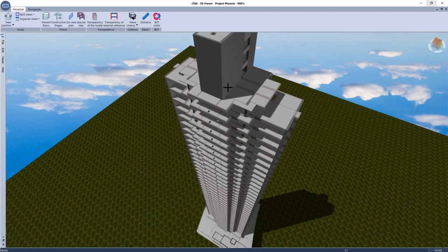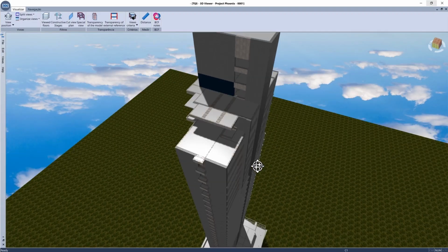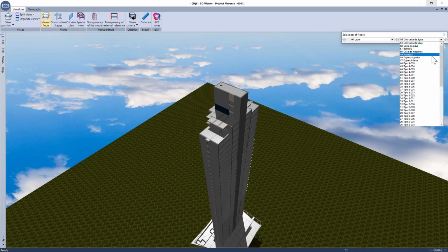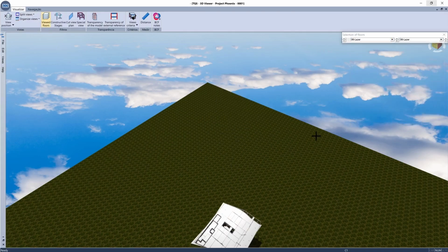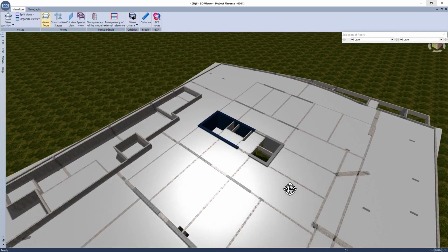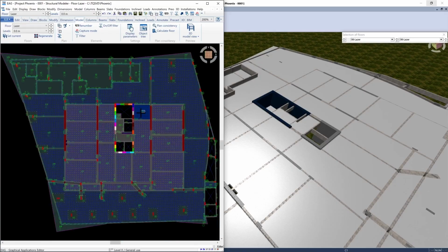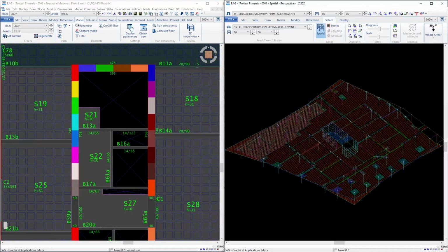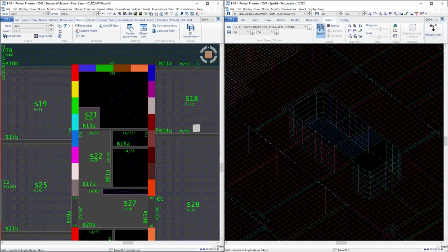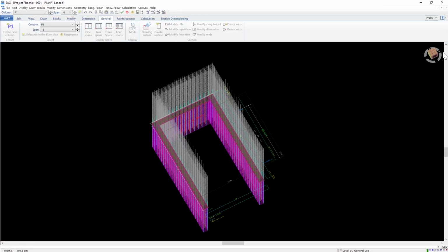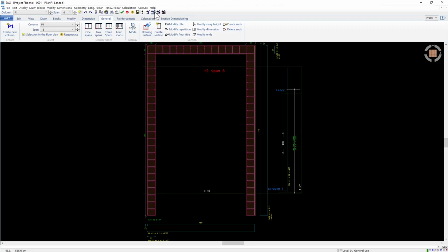Shear walls, as they are surface-like elements, are treated differently in TQS. They can be composed of several strips, common in rigid cores of tall buildings. They are modeled by a mesh of bars representing the strips, with full control over their discretization, with bending and torsion being analyzed. The design and detailing of their reinforcement takes into account particular effects, such as localized second-order effects at their free ends.